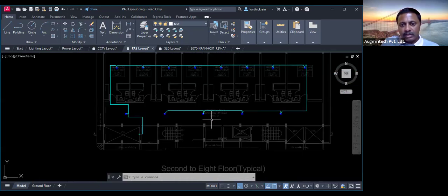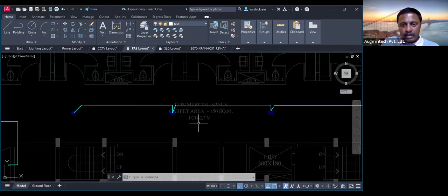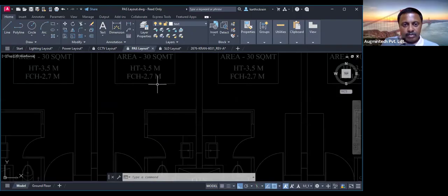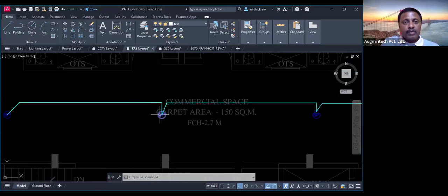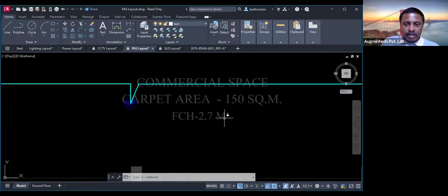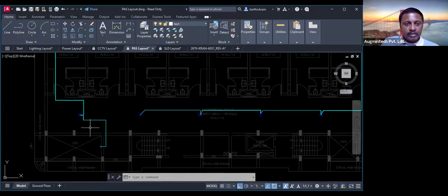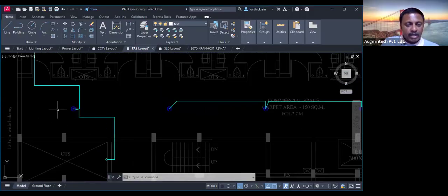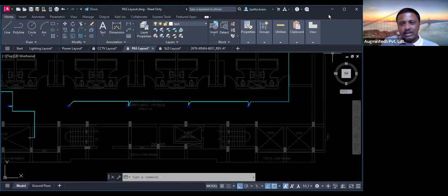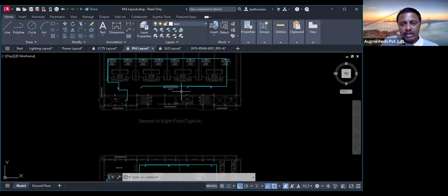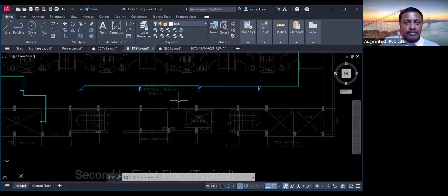And in case of the corridor, as I told you, the height is almost the false ceiling height, which is considered to be 2.7 meters, right? In the false ceiling only we are going to install these speakers. So just ensure that it should be a 5.4 meters distance. In that case, you can include one or two more speakers, and adjust a little bit over here and there.